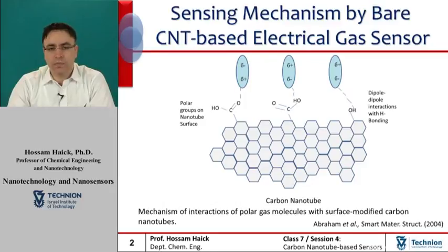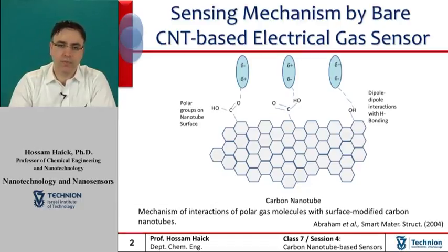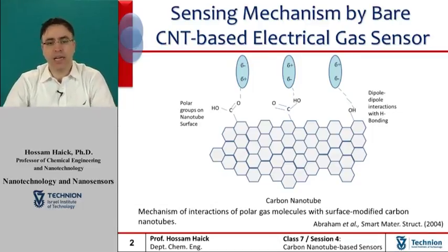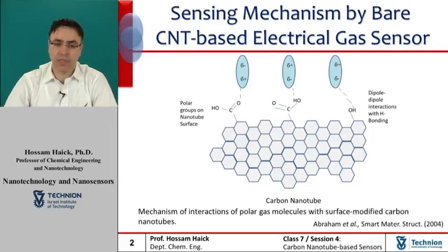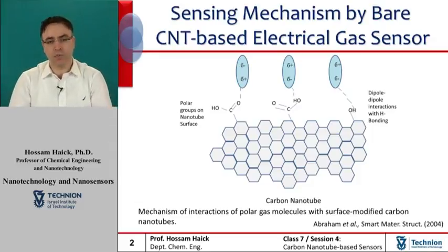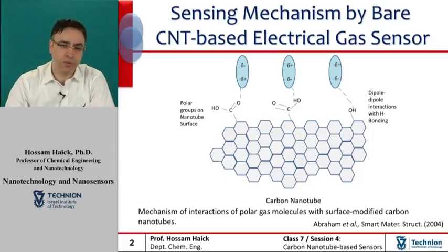For example, acid oxidation increases the surface area of carbon nanotubes, creates sidewall defects, and simultaneously introduces functional groups at the defects on the nanotube surface. Another example is that acid treatment can also be combined with plasma treatment for a two-step functionalization, and plasma treatment can also be implemented as a standalone process to create oxygenated groups.